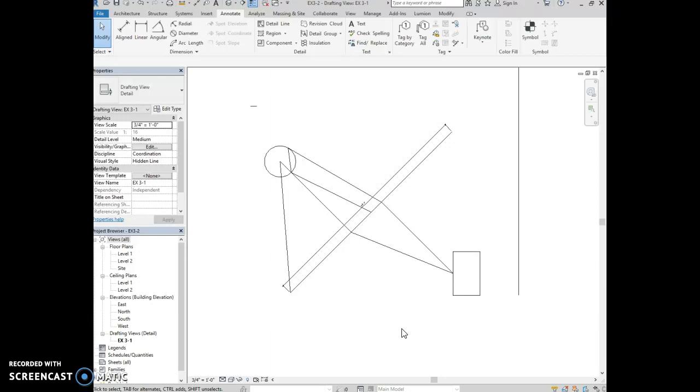What I want to point out next is reminders. Let's talk about reminders in Revit. Revit is configured to remind you to save every 30 minutes so you do not lose any work. It is recommended that you do not simply click cancel, but you click save the project. So on page 3-19 of your book, it's giving you an example of what the reminder will look like. If you take a lot of time to do your project, every 30 minutes a reminder box will pop up, and when the reminder box pops up, click save the project.